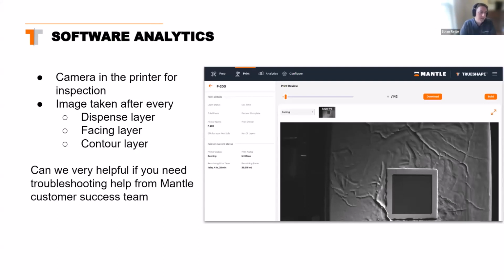We have an overhead camera within the printer. It's going to take a few pictures every single layer. For example, it's going to take a picture after you've dispensed, after you've come through and faced that layer, and it's also going to take a picture of every single contouring layer. This is very helpful for the inspection process because if you need to go back and see maybe something went wrong, it's very helpful. It's also incredibly helpful if you ever need troubleshooting help from the Mantle team, because you could send these images to our team. They can look at them and help you troubleshoot if anything went wrong and why it went wrong. I'd be able to help you over the phone because we're able to see all of that within the printer when you share it with us.